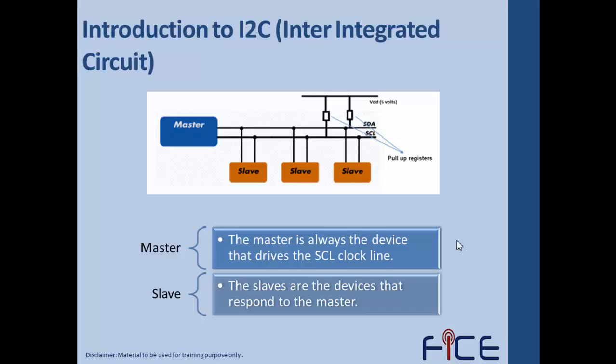I2C stands for Inter-Integrated Circuit Bus, and I2C is a small area network which connects ICs and other electronic systems. Originally, the I2C bus was intended for operation on single-board PCBs, and the I2C bus is a synchronous serial signal that requires two wires to carry the information between a number of devices.